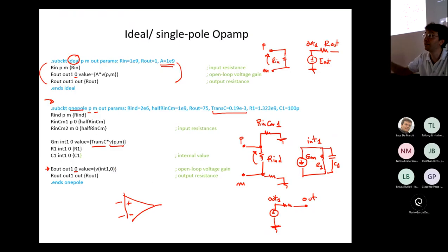And then you test the realization of the low-pass filter with the 1 pole solution. You may have some difficulties in meeting the specification with this second subcircuit, because this is much different from the ideal one.